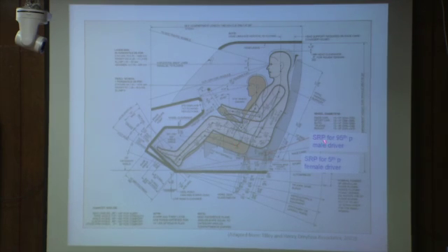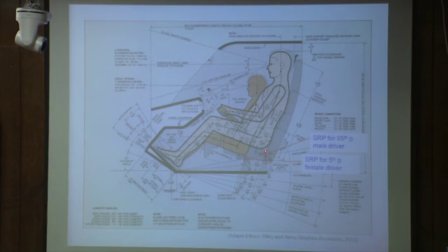Now you can understand the relation between SRP, the seat reference point, and the H point. The seat reference point is located on the seat, but its position may change as per the shifting position of the seat. As the seat is moved forward or backward, the position of SRP changes in 3D space, but in relation to the seat, the position of SRP is fixed.